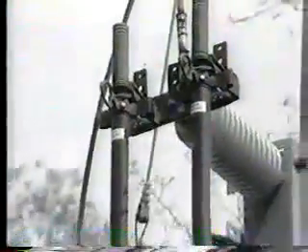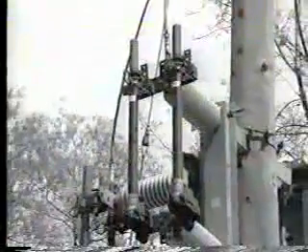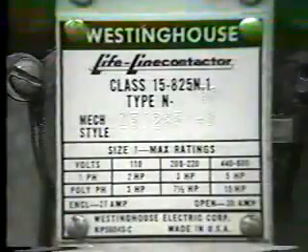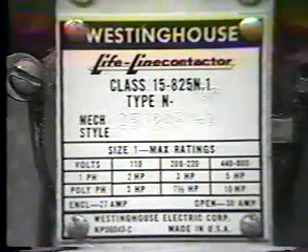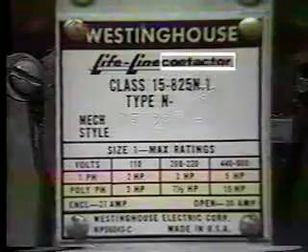On the distribution system, fuses are often used in place of the relay circuit breaker combination. The fuse is not so fast or accurate as protective relays, but it does provide satisfactory economical protection for distribution transformers and feeds. Another type of protection frequently encountered at utilization voltage of, say, 480 volts is the direct acting contactor. In one common type, overcurrent causes thermal contacts to open the circuit. In another type, a built-in relay opens the contactor.